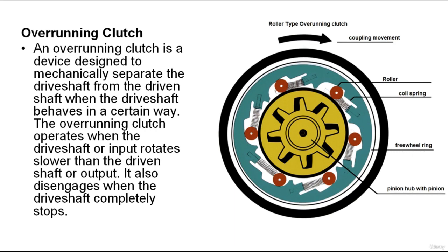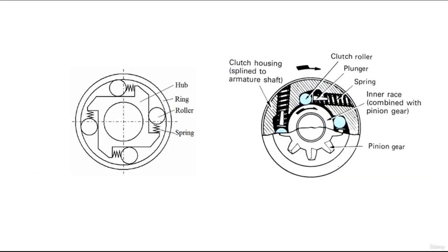At this higher speed, clearance exists between the inner stator race and hub. The rollers at each slot of the stator are pulled around the stator hub. The stator freewheels or turns as a unit.